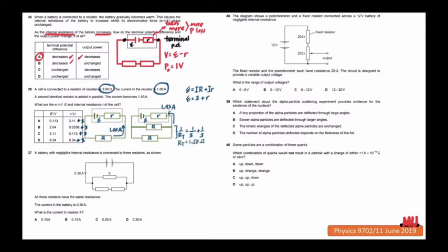Now we can follow the formula from the first diagram as they resemble each other now, with R 3 ohms here but 1.5 ohms here, and current values 1.0 ampere here and 1.93 here. EMF equals 1.93 times 1.50 plus 1.93 times the internal resistance R, following that formula.